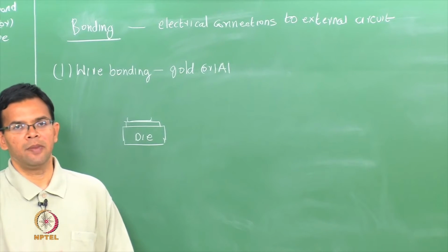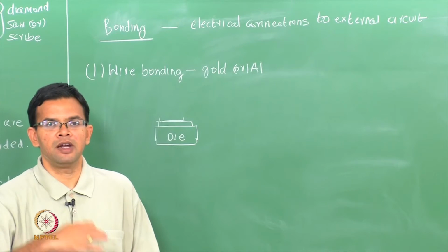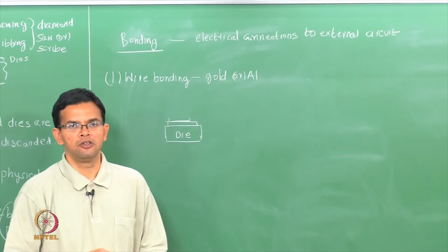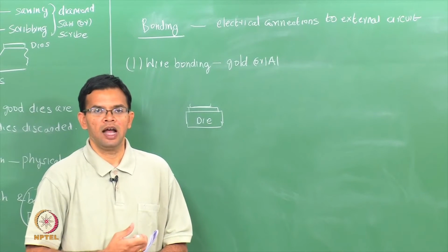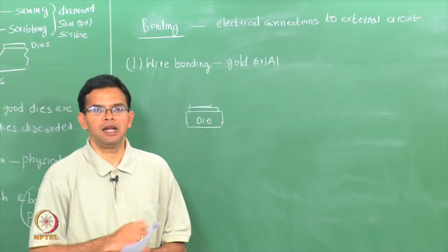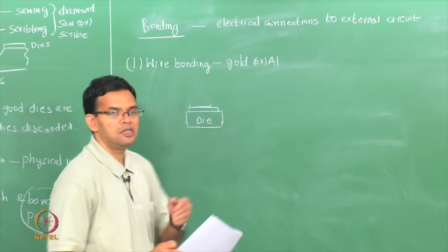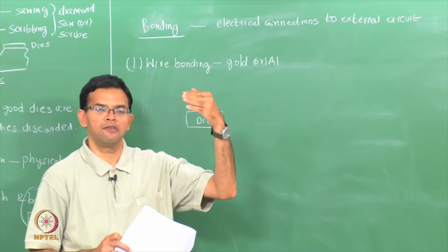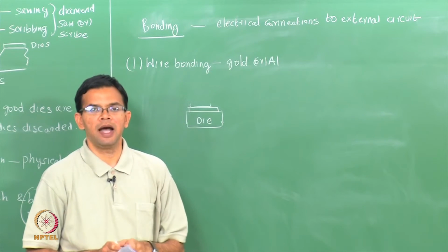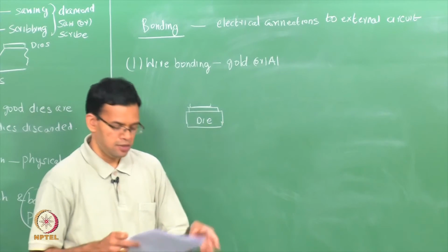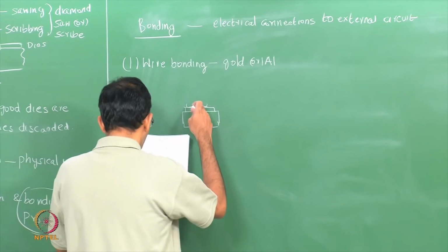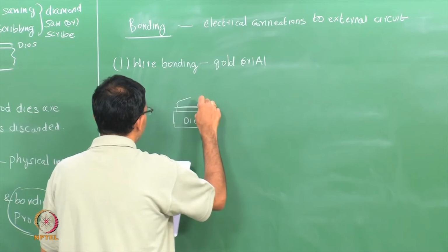When we looked at the metallization, we saw there were different levels of metallization. Some of the newer transistors or newer IC circuits have essentially 11 levels of metallization. So, the connection is made to the topmost level. These in turn feed back to the transistors and the other components of the IC. So, you have a bond that is being formed.